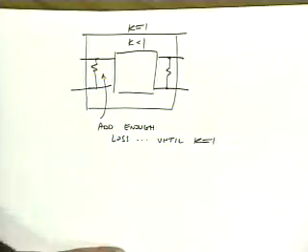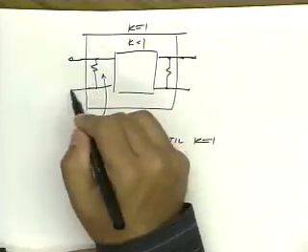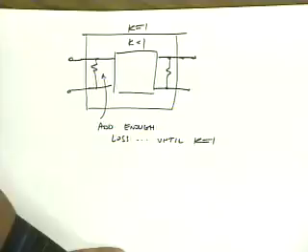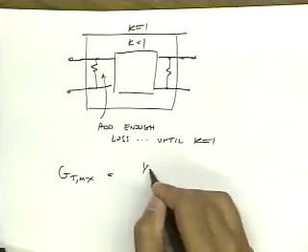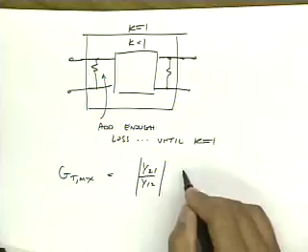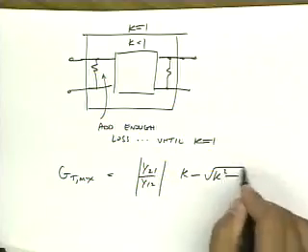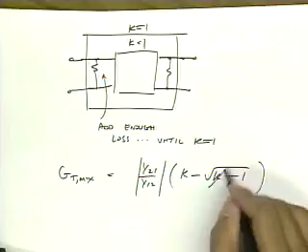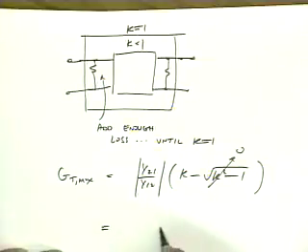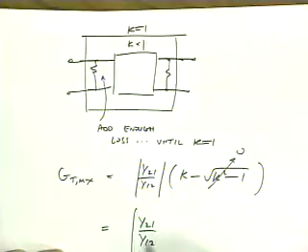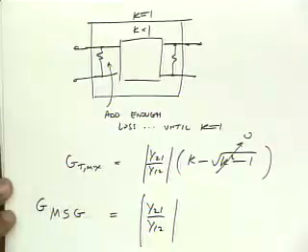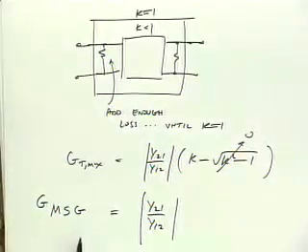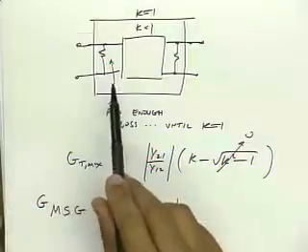And then we actually have something from the external two-port here that looks unconditionally stable. And so then the expression GT max applies. So GT max in that case is y21 over y12 times K minus square root of K squared minus 1. But now K is equal to 1, this term's 0, this term's 1. So then it just breaks down to this expression, and we call this the maximum stable gain, or sometimes G maximum stable gain. And it's the maximum stable gain because we've stabilized our amplifier on purpose.